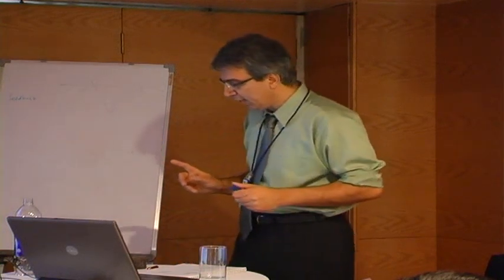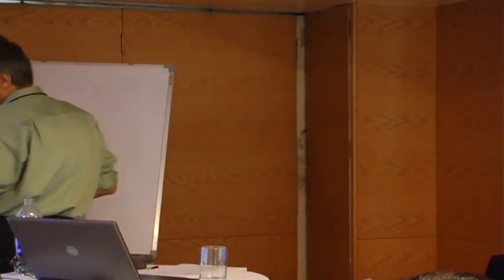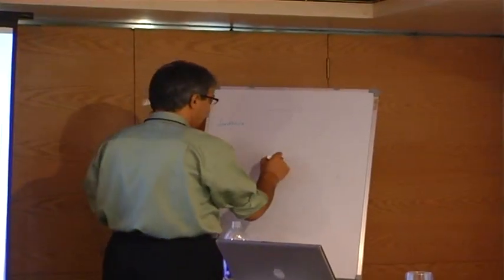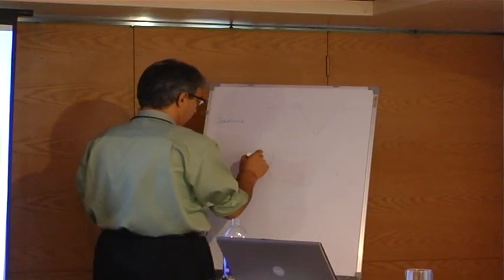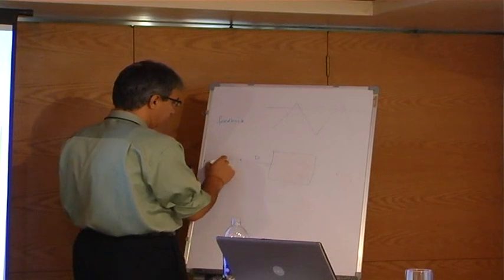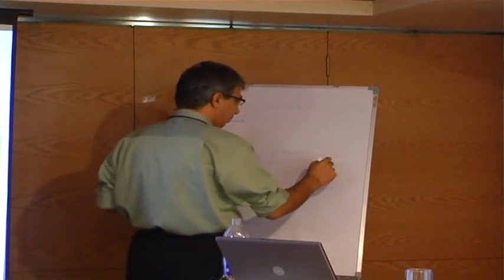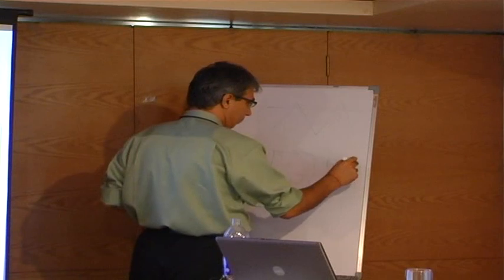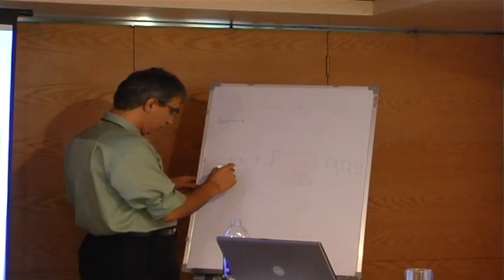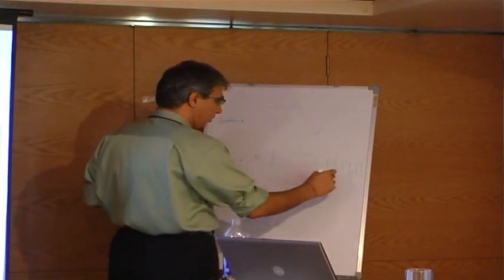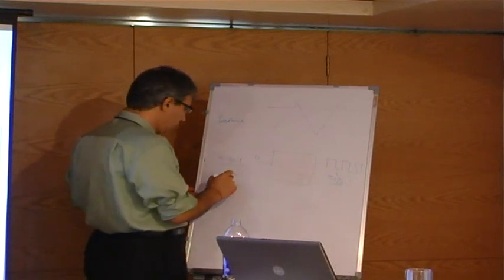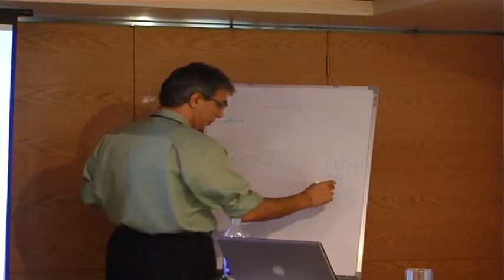And also here, with this block, all I have to do is give the duty cycle command of 0 to 1, and I basically get pulses. Based on my duty cycle command, let's say if I give a duty cycle of 0.5, I get 50% duty cycle pulses. If I do 0.99, I have 99% duty cycle pulses.